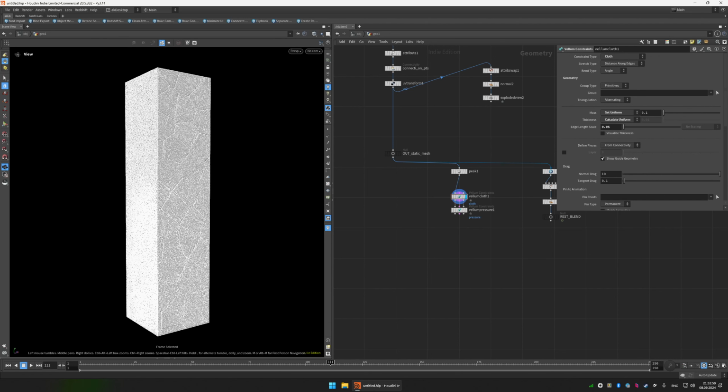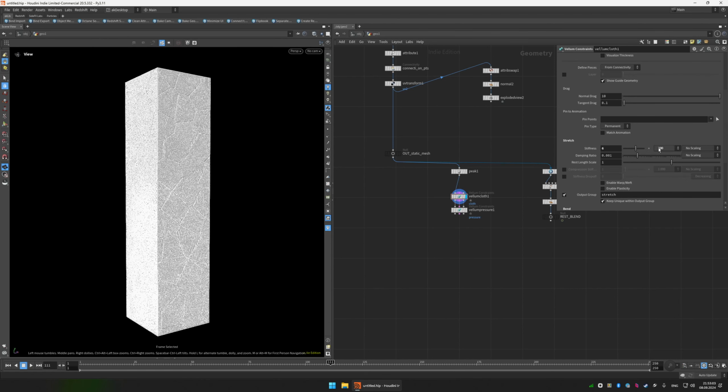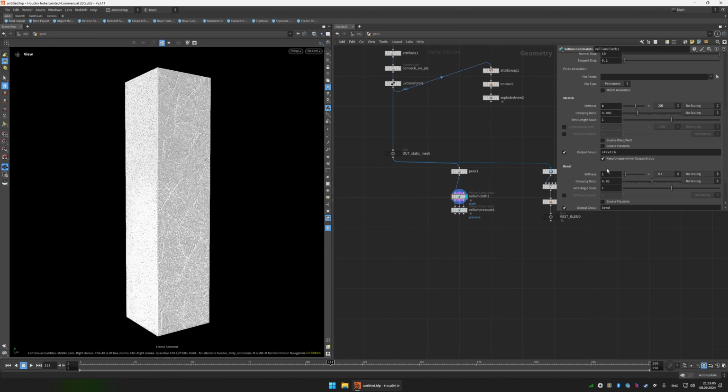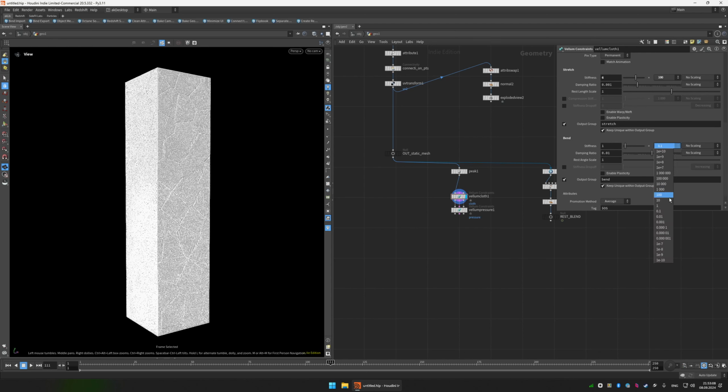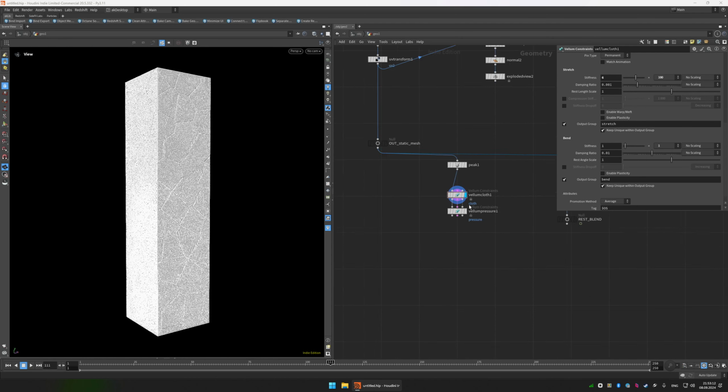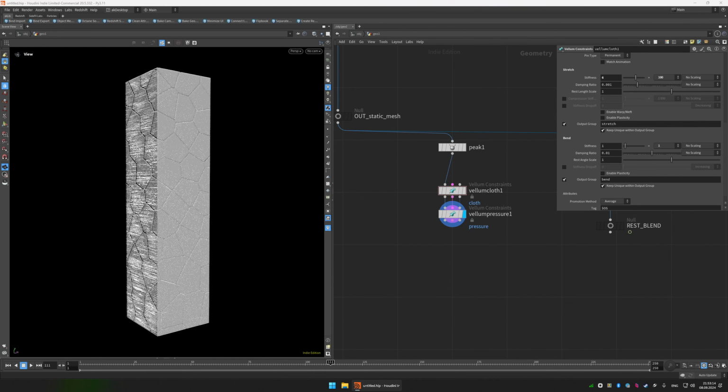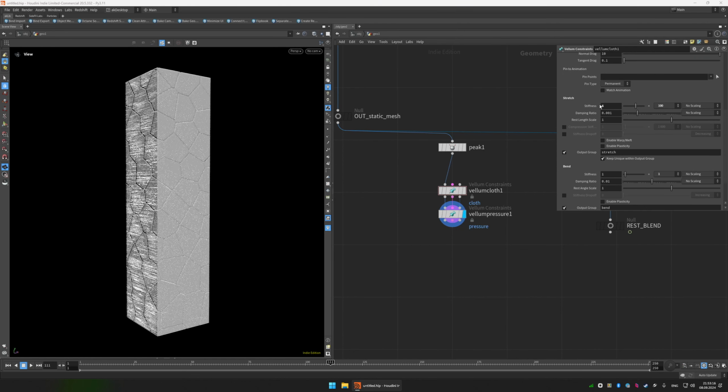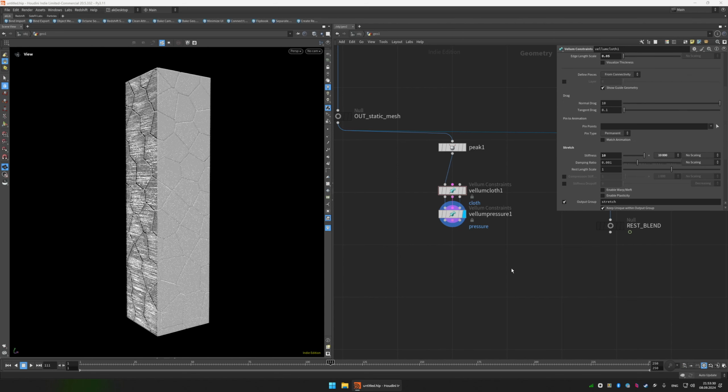And then the parameters: the stiffness of the stretch constraint is default. I upped the bend a little bit, and that was pretty much it. In the pressure constraints, what I did was I set the stiffness to 10 and the multiplier to 10,000. So I want them to be more balloon-like, with less stretchiness, bendiness, stuff like that.